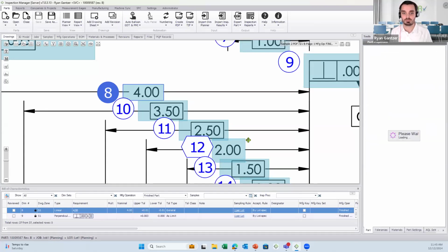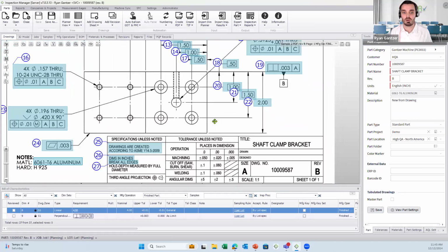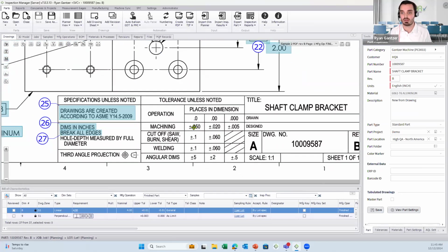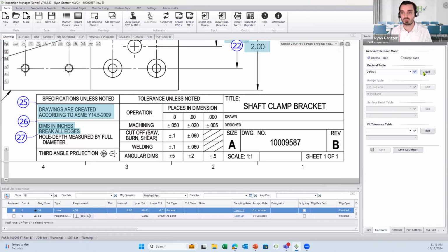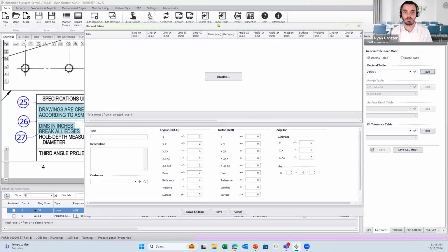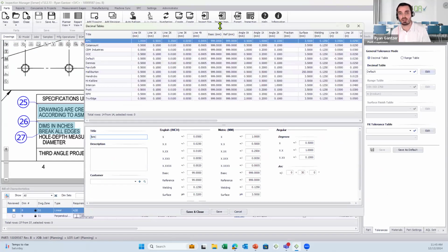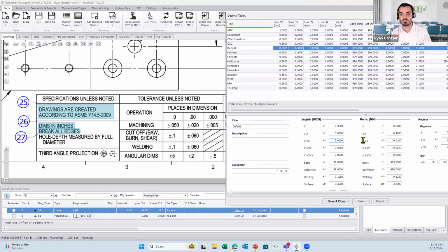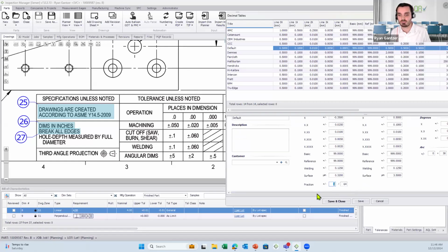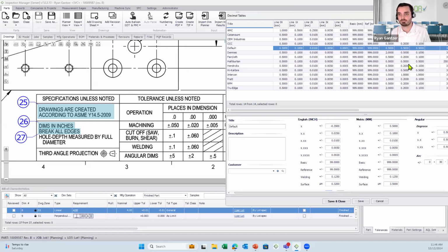So to show, because if you recall, we're not looking inside of this tolerance block. But if I go to this tolerances tab down here below, this will give you a peek into kind of where these tolerances are coming from. So that plus or minus 10 thou, right? Based on 2 decimal points. In English, we're going to plus or minus 10 thou. Again, if the tolerance isn't on the print itself. We also support metric, as we showed, fractions, and angles.